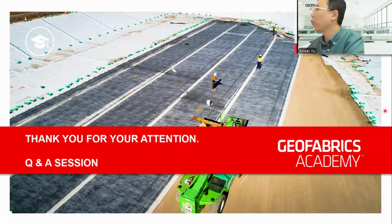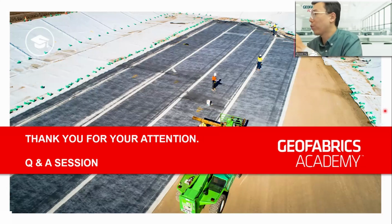Simon just asked a question. Just curious, how do you separate the sample in a large direct shear box? A couple of ways to do so. At the moment, some designers request the samples be hydrated separately outside of the shear box and then installed in the shear box. There are certain ways of doing so, but you will need to control the confining pressure, and also how to control the bentonite loss on the edge. So that's an important topic.